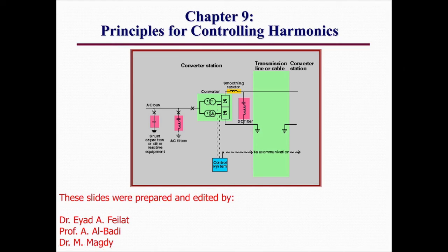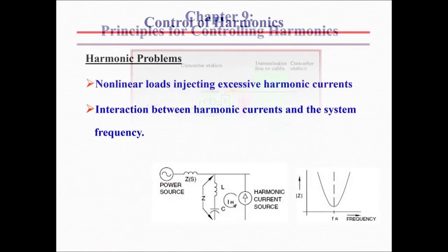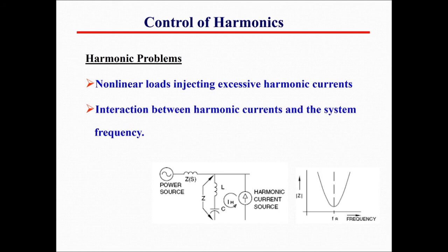Bismillahirrahmanirrahim. Today we're going to talk about chapter 9, which is about principles for controlling harmonics. Harmonic problems are due to the nonlinear load that injects excessive harmonic current, and also interaction between harmonic current and the system frequency, because we said that it's going to create resonance.